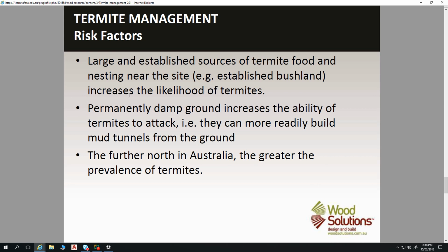I didn't get there for another 2 weeks after it was delivered, broke it apart and had termites starting to eat the face of the timber already. So that's within 2 weeks, the timber was getting wet, sitting on wet ground, but within that short period of time, you get termites into the wood. So it can happen very quickly, especially in the presence of moisture on the ground.